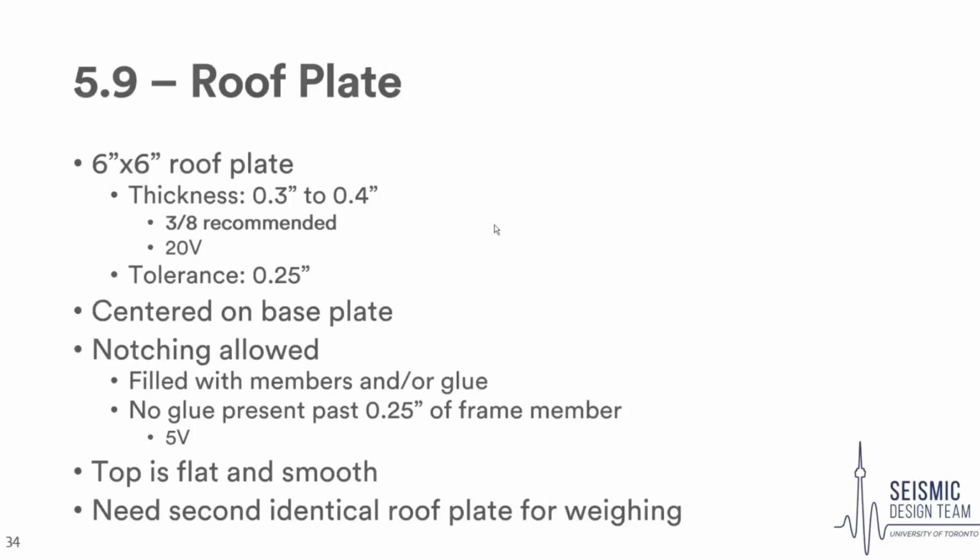So we had to tear off our existing roof plate and rebuild. We went to Home Depot, bought 3/8 wood, cut 2 new roof plates, and installed it. That was a big hassle that I wish never happened, and was the most stress I've had in a long time. So use 3/8, because in case anything happens, it's widely available everywhere.